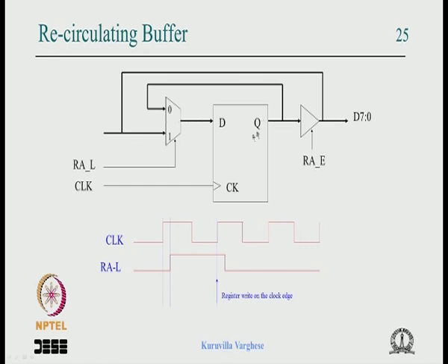So input gets latched, and because of the state machine decoding, the latch signal comes delayed and is made 1, and the input is coming from some register clocked by the same clock. So it starts appearing here, and it has all the time till the next clock period, and upon this clock edge, the data gets latched here. So it's very clean.